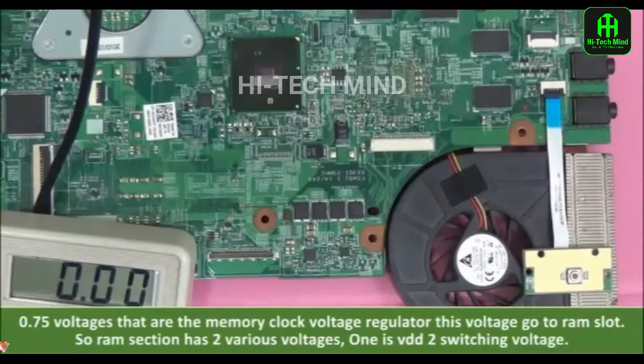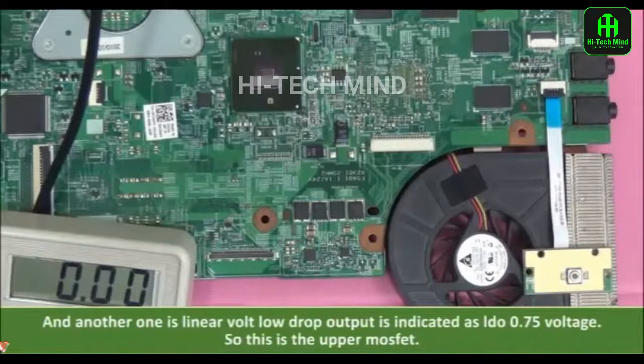0.75 voltage, that is the memory clock voltage regulator. This voltage goes to the RAM slot. So the RAM section has two various voltages. One is VDD2, the switching voltage, and another one is the linear voltage, low drop out, indicated as LDO, 0.75 voltage.